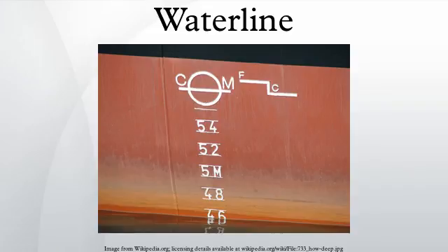The waterline is the line where the hull of a ship meets the surface of the water, in concept or reality. Specifically, it is also the name of a special marking, also known as the International Load Line, Plimsoll line or Waterline, that indicates the draft of the ship and the legal limit to which a ship may be loaded for specific water types and temperatures in order to safely maintain buoyancy, particularly with regard to the hazard of waves